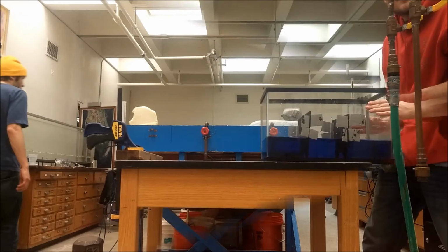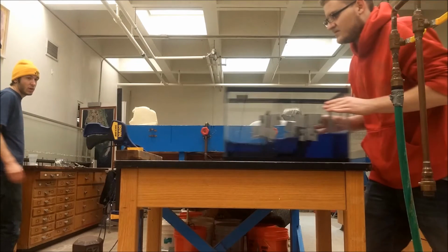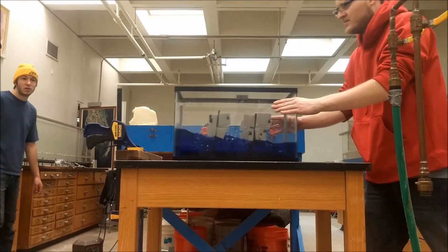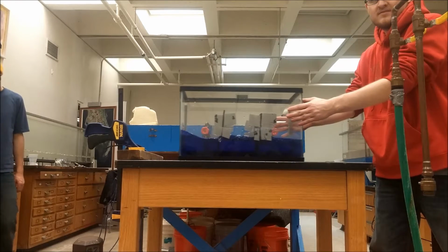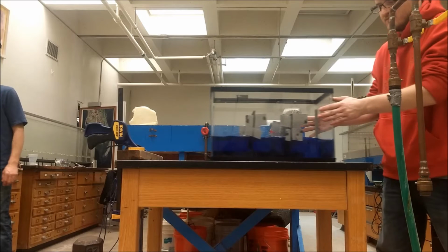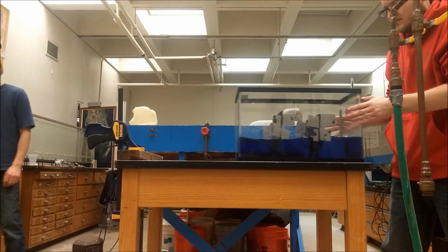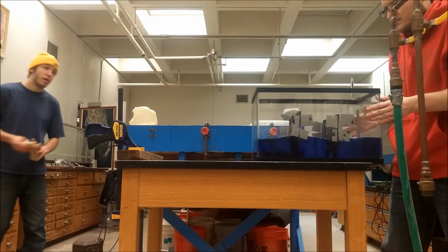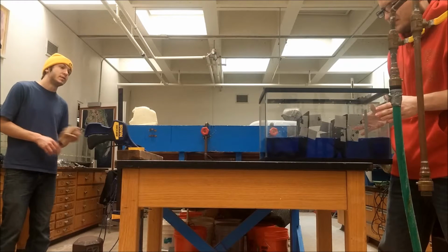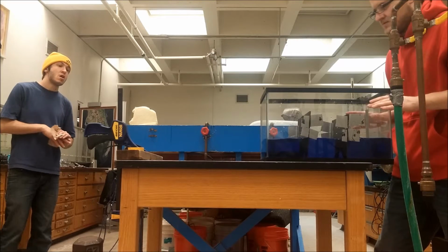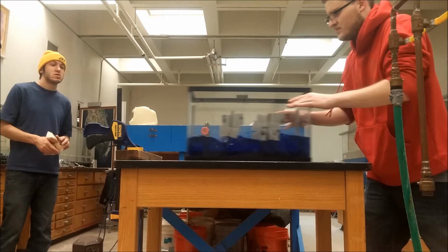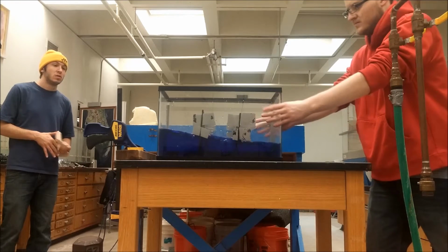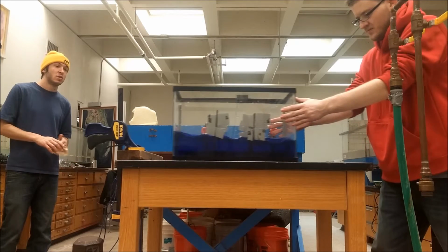The final slow motion video demonstrates 2 baffles being used in order to decrease the height of the water within the tank when there is linear acceleration. Again, we see the water reaches an even lower level than one baffle and settles down faster to steady state than the other 2. This further reiterates the point that the more baffles that are used, the less the fluid within the tank will slosh around.